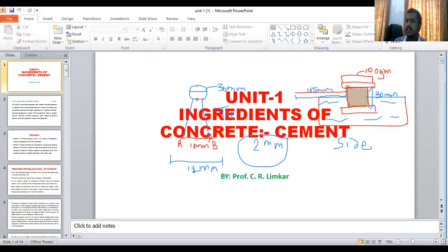So you are going to fill the cement paste. How are you going to prepare the cement paste? You are going to take 400 gram of cement. You are going to add 0.78% of the water which is required for your consistency. You are going to prepare the cement mix. What is the time to prepare the cement mix? Within 3 minutes, you have to prepare the cement mix.